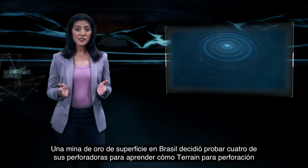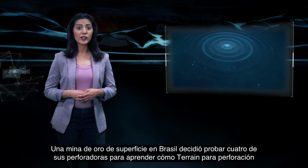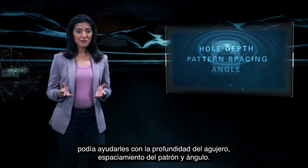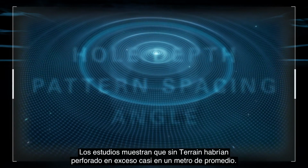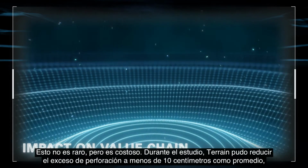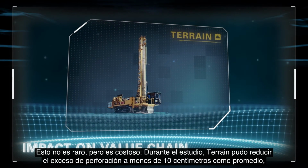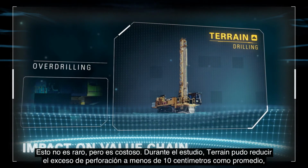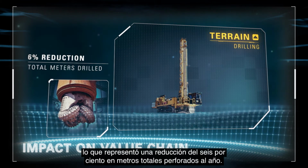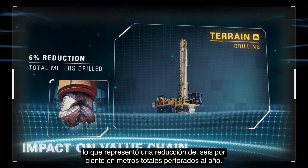A surface gold mine in Brazil decided to test 4 of their drills to learn how Terrain for drilling could help with hole depth, pattern spacing, and angle. The study showed that without Terrain, they had been over-drilling by almost a meter on average. That's not uncommon, but it is costly. During the study, Terrain was able to reduce that over-drilling to less than 10 centimeters on average, which represented a 6% reduction in total meters drilled per year.